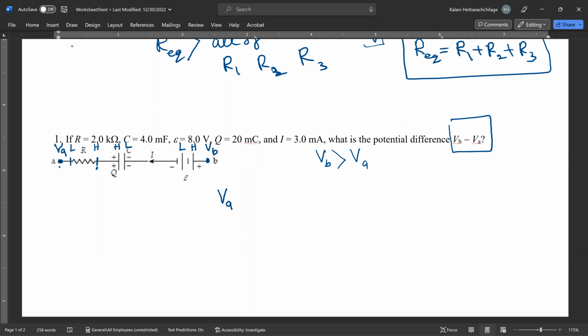So that means this resistor, that's Ohm's law, the I times R amount, the potential increases from left to right, but right to left it is decreasing, okay? But I am going from left to right. Because of that, the potential is increased by the I times R amount. So now the next one is my capacitor.